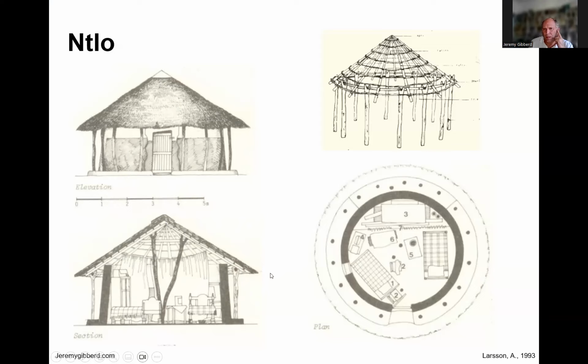In winter, what happens is that you get low angle sunshine. It hits these high thermal mass walls, they warm up, and when the sun goes down, these walls are warm, particularly the west facing walls, and that re-radiates heat into the room, and those rooms are nice and warm at night. So again, very comfortable, well-attuned buildings.